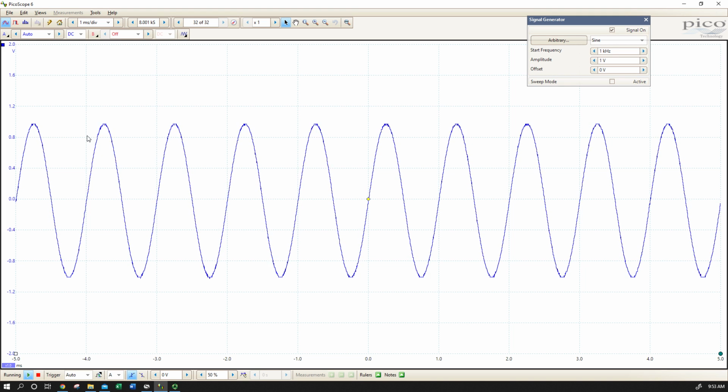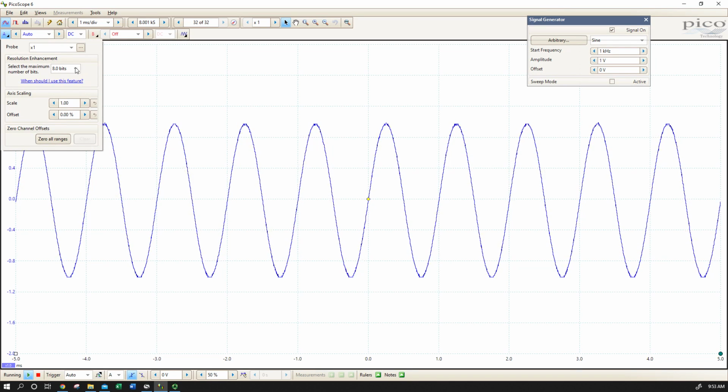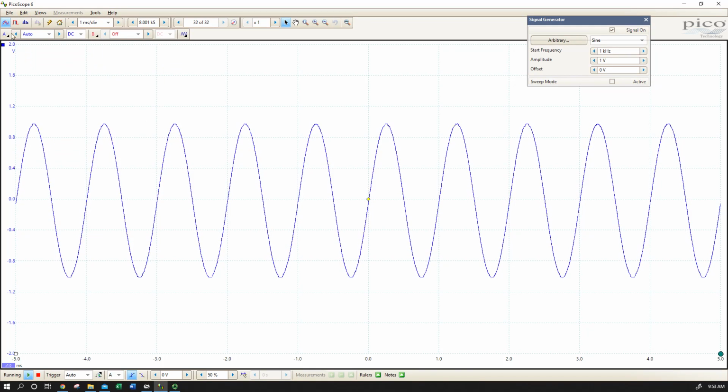Okay, what's important about what we're seeing here? This is the voltage drop over the whole circuit. So let's take a look. We can see there's a little bit of noise here. We can smooth that out a little bit by oversampling on our signal there, which we can get to with our display over on A. Okay, so now we can see a little bit better. So this is the whole circuit.